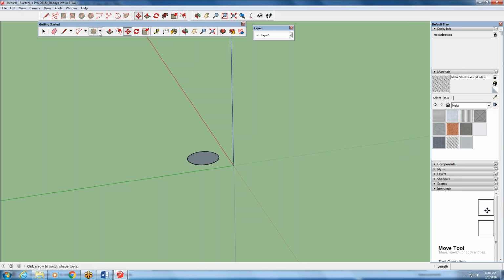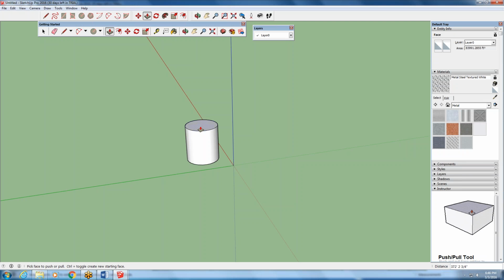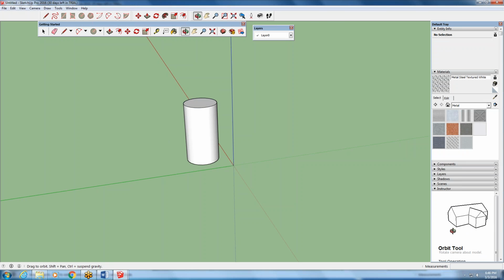If you did create a cylinder, although it doesn't have to be, how does it know that we are push-pulling it up to begin with? How is it thinking in a 3-dimensional way? It has to think of it in relativity to these different axis points. So the colored axes come into play. If we want to move it up, we go in the blue direction. If we want to move it back, we follow the green direction, because the green axis happens to run from the front to the back of the screen.